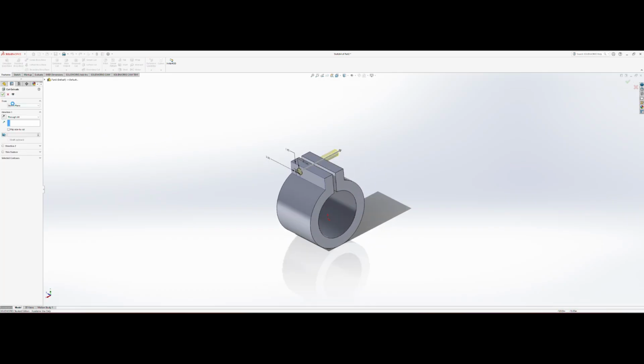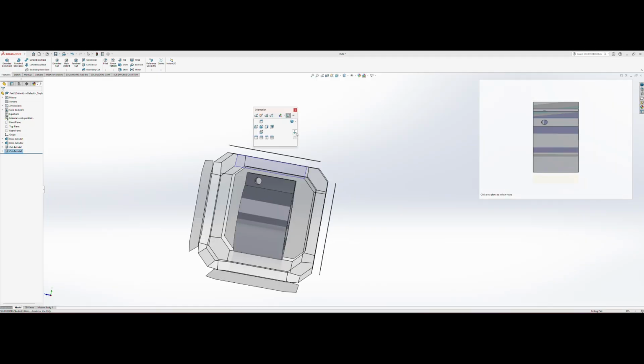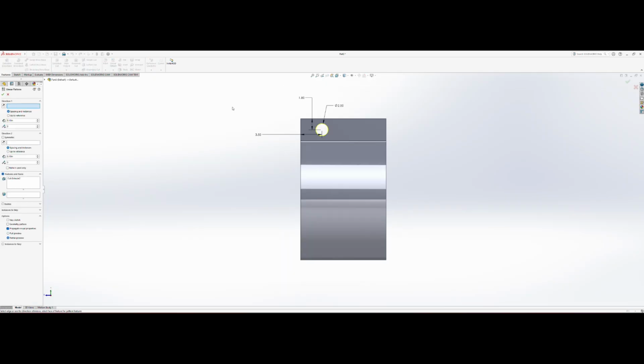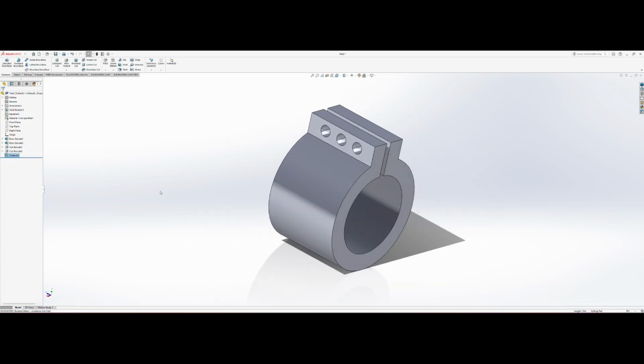through all, so that's what we need, but I'll need 3 more, so I'm gonna use a linear pattern in this case. Alright, make it normal, right? And then make a linear pattern, and then direction. I want it to go in that direction. I want 3 instances, and I want it to be 3.5 distance. And then reverse that. That's exactly what I want. Okay, boom.